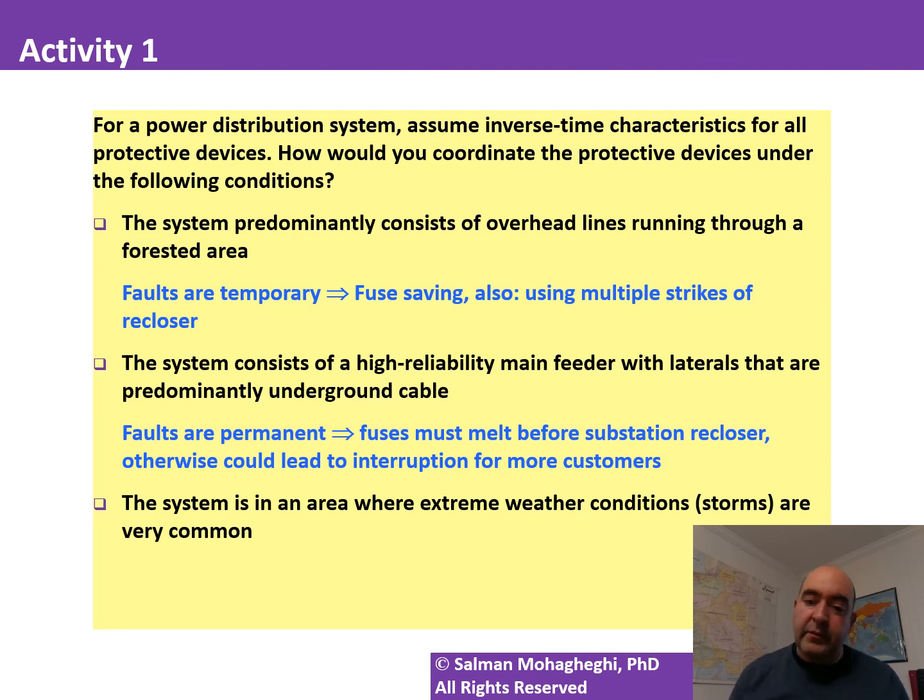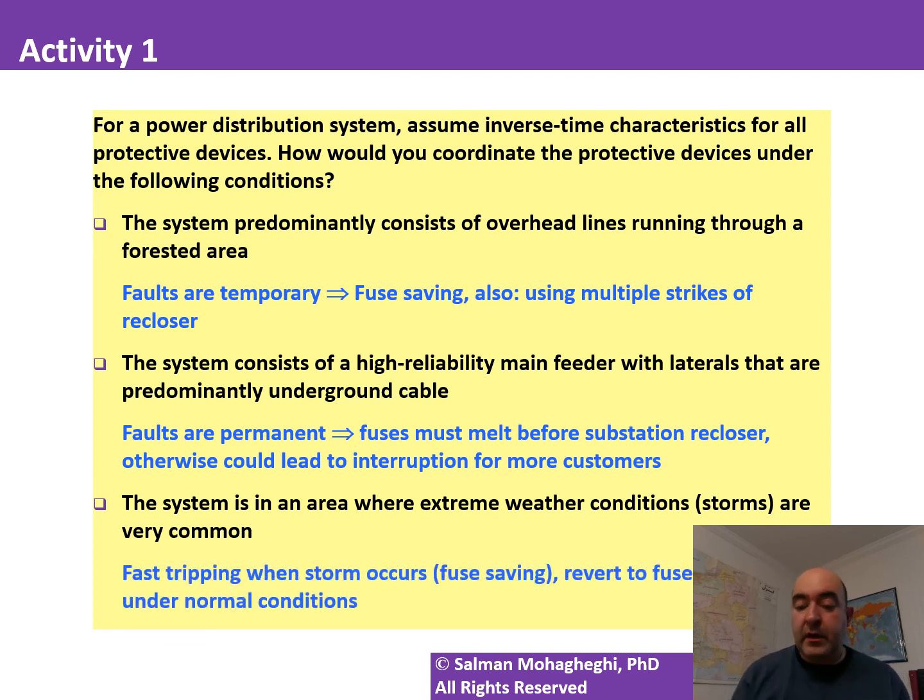So this is somewhere in between, because during the storm, the faults are mostly going to be transient and temporary in nature. However, during normal operating conditions, when the weather is okay and there are no extreme weather conditions, chances are that faults are not temporary. In a situation like that, what we can do is have an adaptive coordination